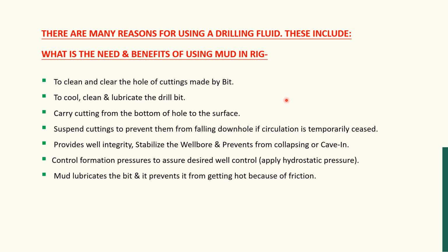Okay, now we will see why this circulation system is important, why the drilling mud is important in the drilling operation. There are many reasons. First of all, it cleans and clears the hole of cuttings made by the bit, because the bit is continuously cutting the rocks, crushing and grinding the rocks.